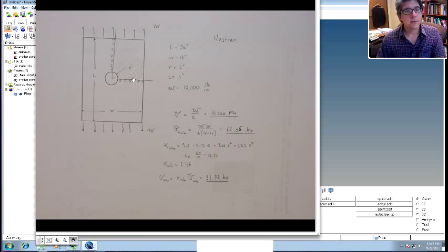Alright, so we've set up the materials and the property cards and then the component, which is the collector that's going to hold all the elements for the quarter plate model. Now we just have to define the geometries and then mesh it. So typically, in practice, you're importing geometries from a CAD package like NX or something like that. And in that situation, or Pro Engineer, you're importing in an IGES file or a native file, and then you mesh that directly. We're actually going to create the geometry in Hypermesh.